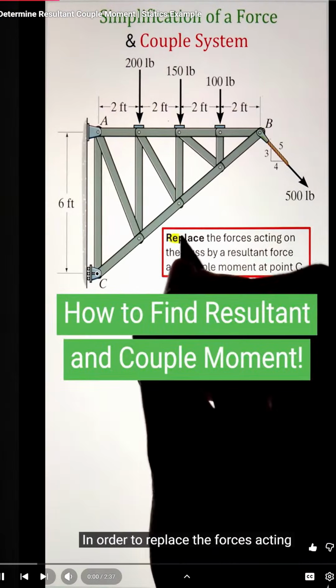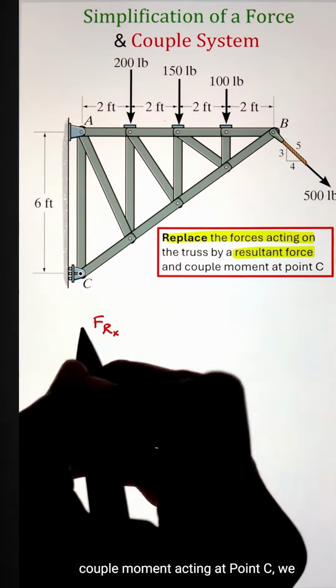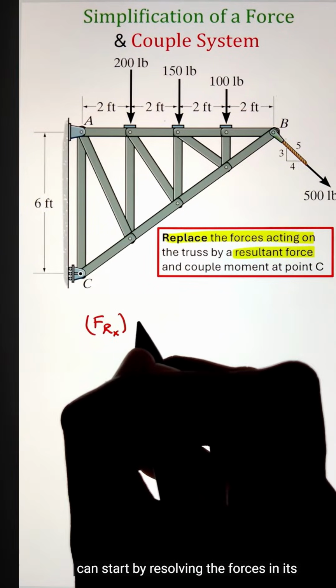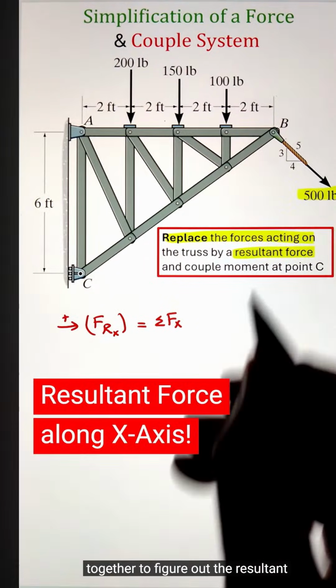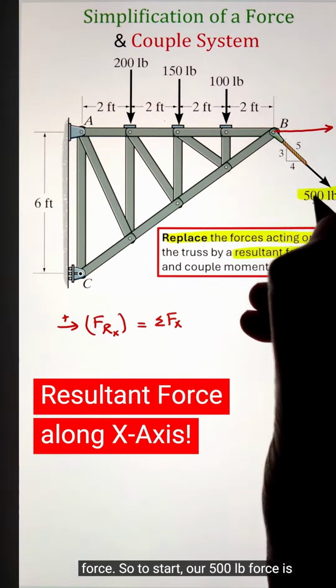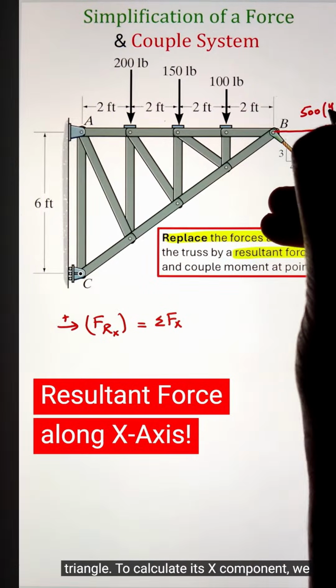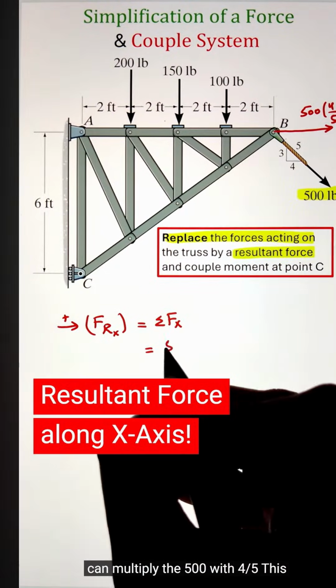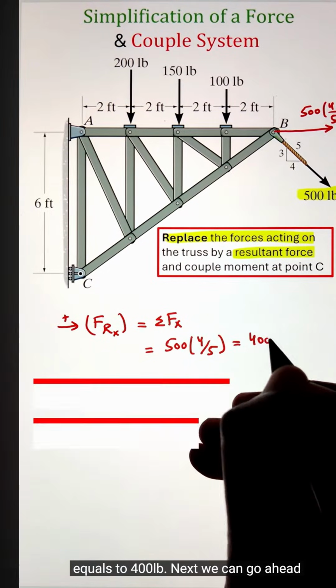In order to replace the forces acting on the truss by a single force and a couple moment acting at point C, we can start by resolving the forces into their x and y components and then combining them together to figure out the resultant force. So to start, our 500 pound force is acting at an angle given by the right angle triangle. To calculate its x component, we can multiply the 500 by 4 over 5. This will give us the x component of the 500 force equal to 400 pound.